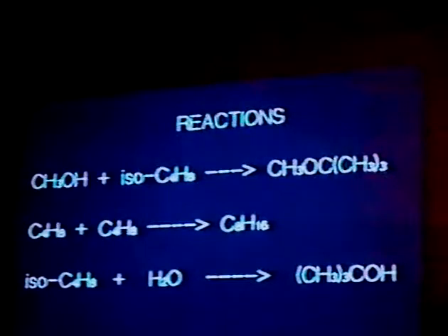There are two major side reactions that occur. The dimerization reaction that I mentioned, of two isobutylenes forming the dimer, and then another reaction of isobutylene and water forming tertiary butyl alcohol. The third reaction, of course, can be prevented by thoroughly drying the feedstocks.